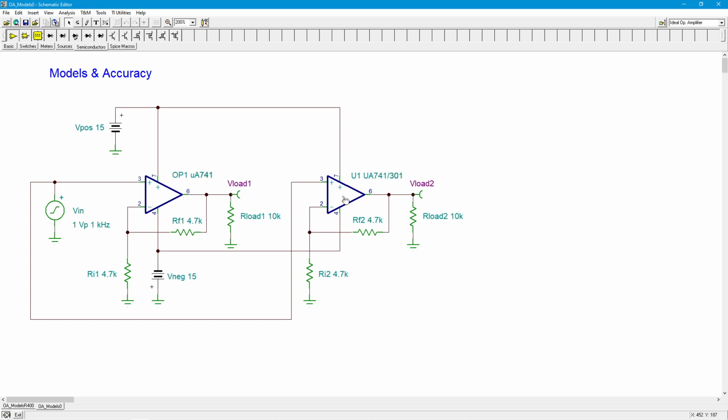So if I do a simulation and I find out that, let's say, the frequency response is within 5% of predicted, I'm not going to get upset about that because, well, look, I got a couple resistors over here, and in the real world, they might be 5%ers, and if they just happen to be off in the right direction, one is high, one is low, geez, my gain might be off by 10%, just because of the tolerance of the resistors in the real world. Because when I buy a 4.7K resistor, I know it's not going to be exactly 4.7K. That's true with all my components. If I have capacitors, the power supplies, you name it.